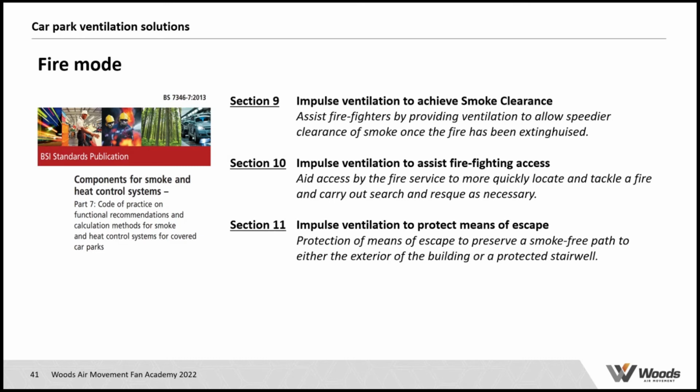Because in most fire service protocols, if there's no sprinkler system or engineered smoke control system in the car park, then it's a question mark whether they will actually do an intervention from the inside, depending a bit on surrounding buildings, but that leads too far for this presentation. So Section 10 is a more engineered solution where we basically provide what we call tenable conditions for firefighters.